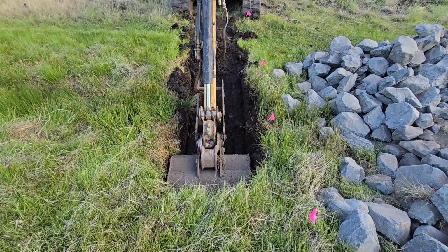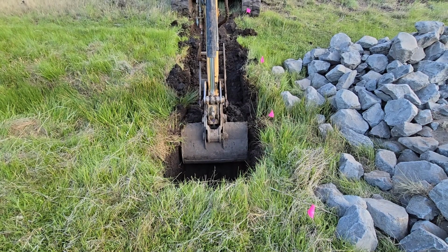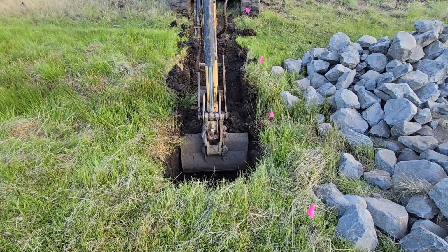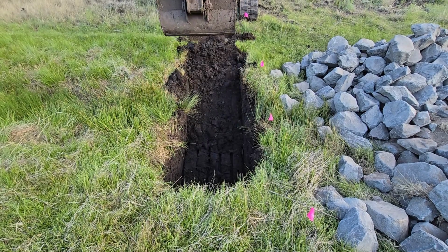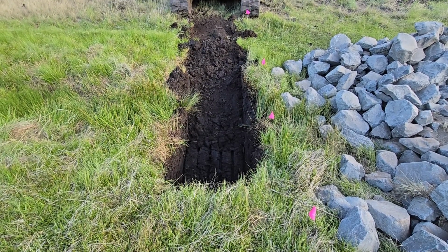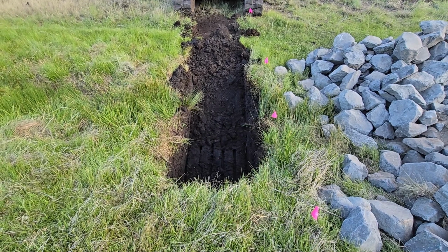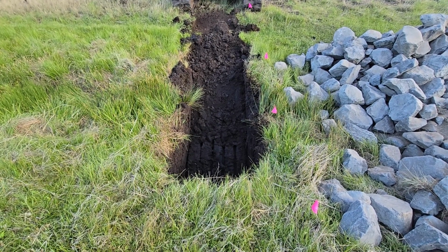Don digs the trench deep enough to cut through a permeable layer of gravel that's carrying water underground. I ask him to dig even deeper until he keys into a thick layer of saturated clay from 8 to 10 feet below the surface. He saves the soil that's high in clay in a separate pile and will later place this clay in the core trench to make a groundwater dam.